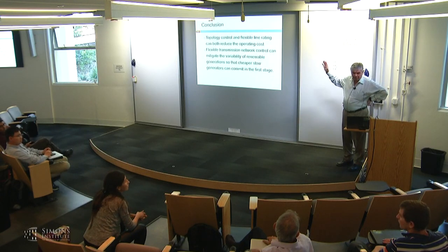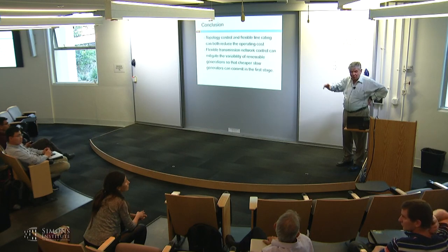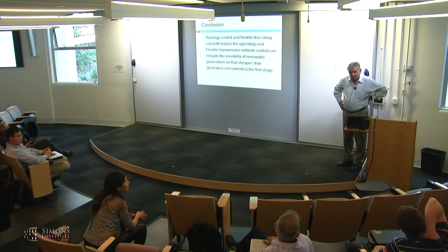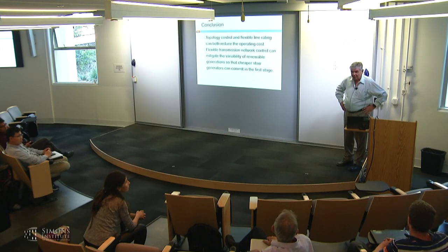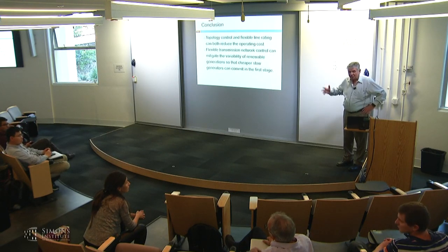So by considering it as a recourse action, we can get away with it. But definitely you have to deal with the NERC constraint. They do allow emergency ratings for mitigation of contingencies. Whether they're willing to consider wind realization as a contingency, that may be a different issue.